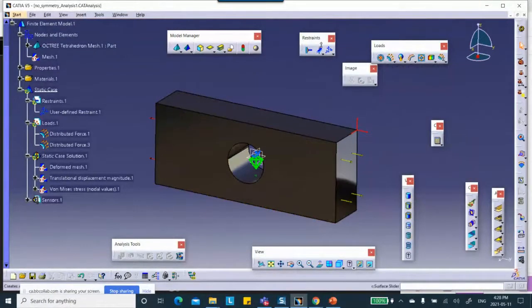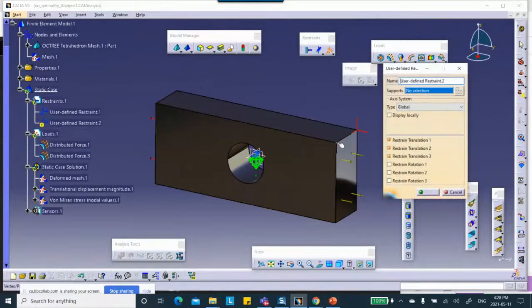Another point, say that point. I'm going to say, you know what? I don't want this thing to spin and rotate about the axis X. So I'm going to say you cannot move in the direction Z. Z is 3. And you cannot move in the direction Y. You can move in the direction X because this thing shrinks due to the Poisson ratio effect. But this will ultimately, if left like that, it can hinge about that edge.